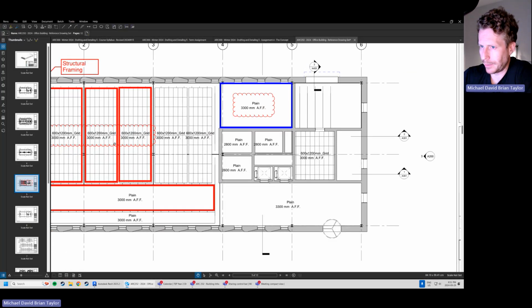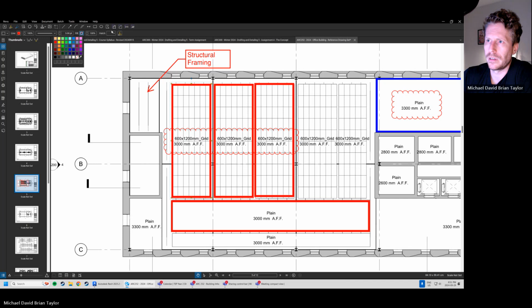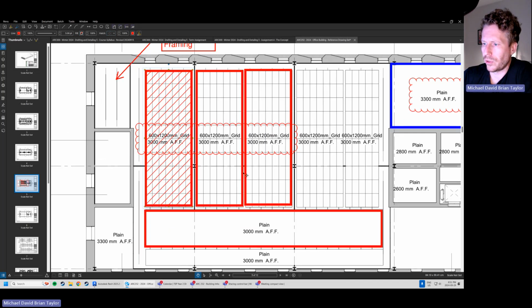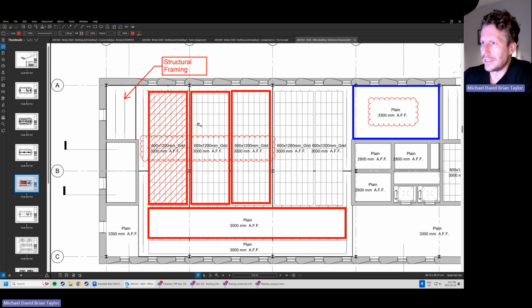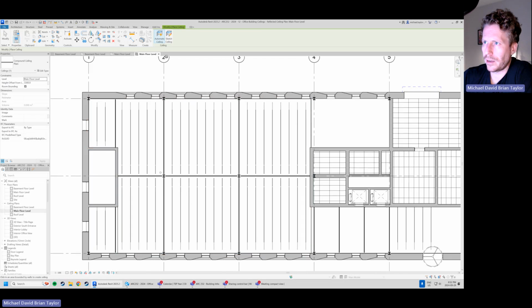Let's jump back to the example here. And why don't we start with this one? Let's give ourselves, just so you guys can see, we're going to start with this little zone here, and then we're going to copy them over. So I'll start with this, and let's make sure that everything shakes out for our little ceiling here. Okay, so back to Revit. Let's try and draw in this zone here. So again, make sure you've got sketch ceiling, and you'll see the menu change from automatic to sketch.